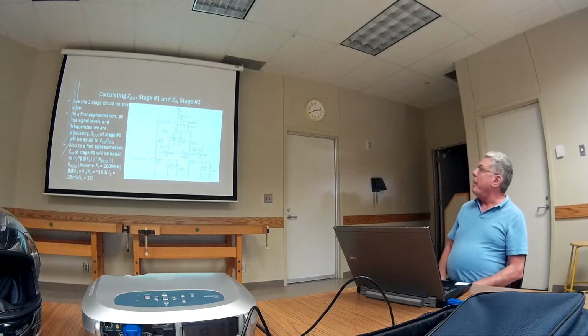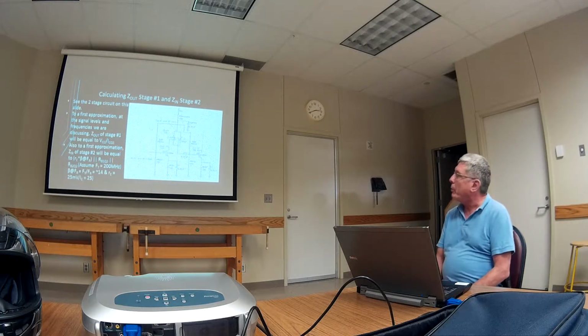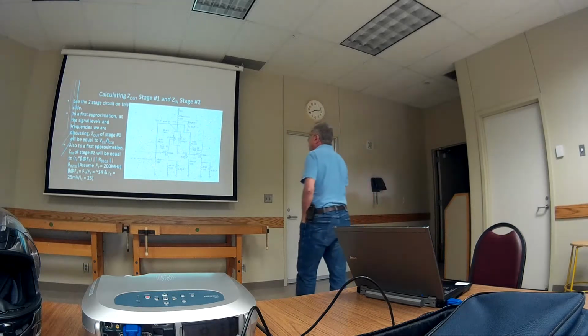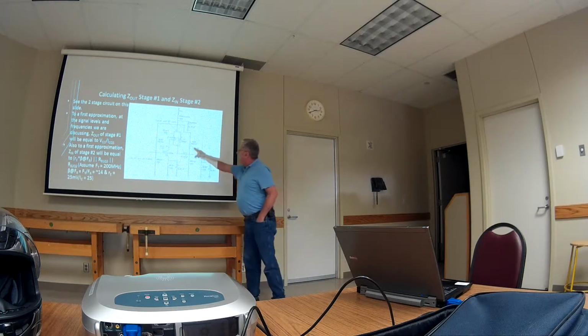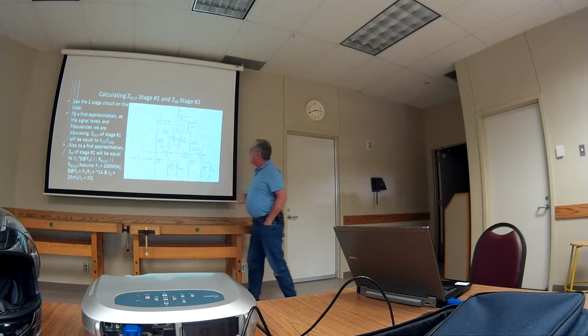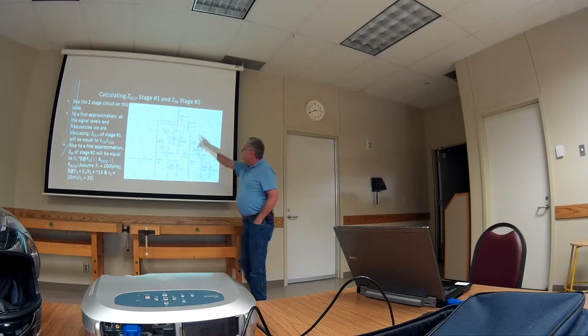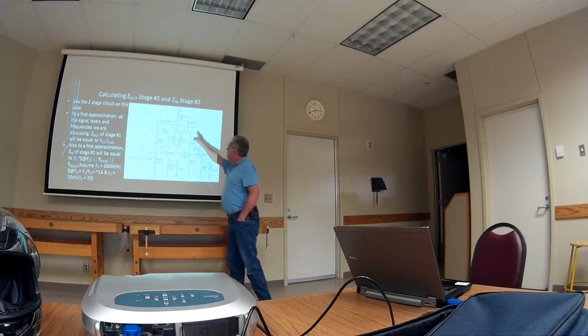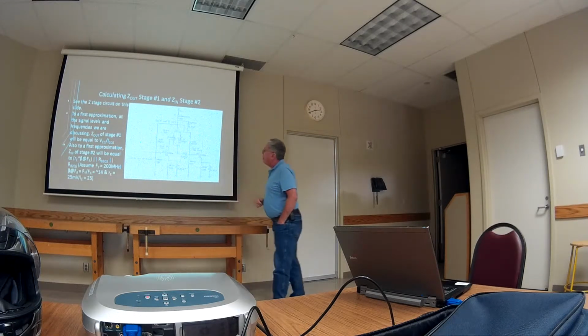So here's the schematic of this thing that I built up. Some of the stuff is the same stuff you'd see at DC. We've got our biasing resistors, and we've got a decoupling resistor up here to keep RF out of the DC, so it doesn't end up talking to other stages. Bypass cap up there.